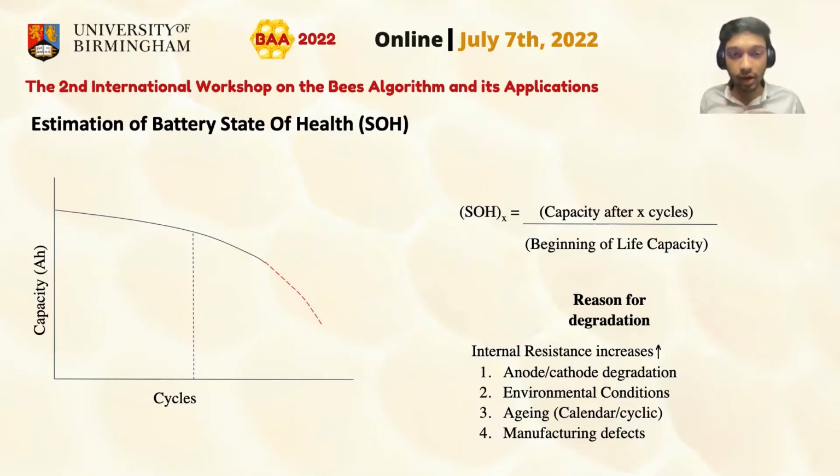cells. Several factors such as temperature, age, charging-discharging cycles, operational voltage, and operating current affect the state of health of the lithium-ion battery. Moreover, other parameters such as the type of charging used and extreme climatic conditions also affect the SOH of the battery.